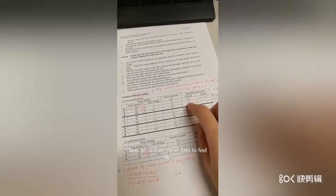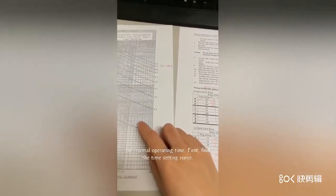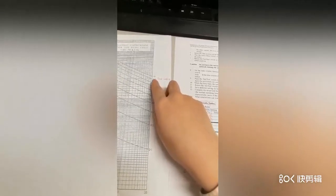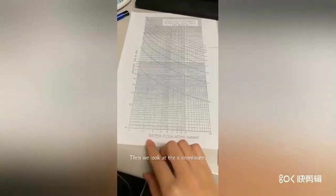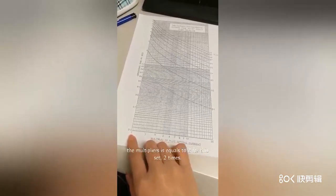Now we use this data to find the normal operating time. First, find the time setting curve. The time setting is 1, so it corresponds to this curve. Then we find the x-coordinate. It equals 2 times.